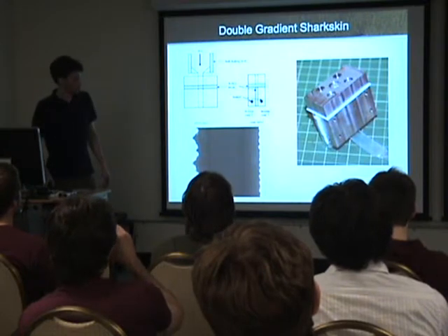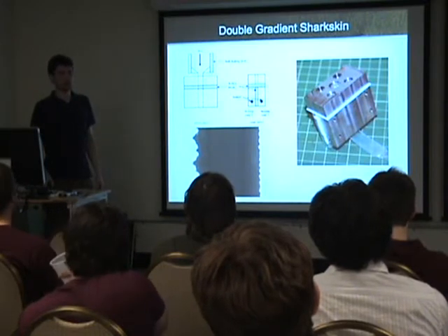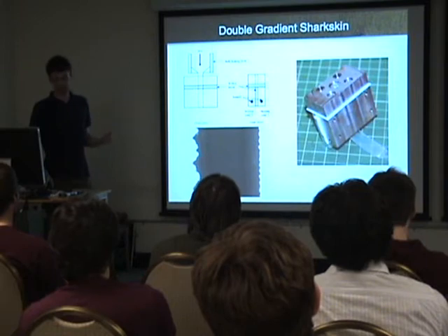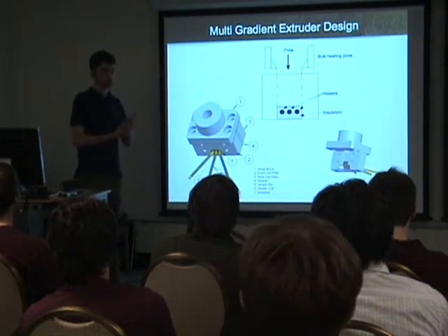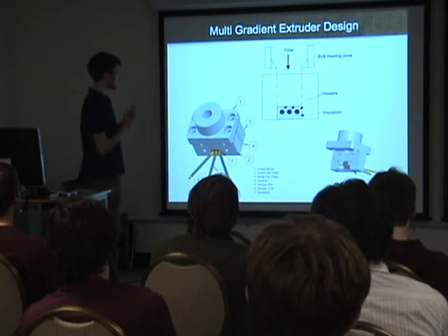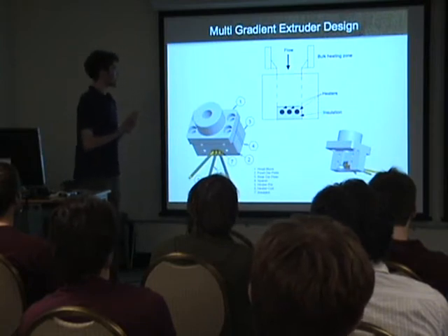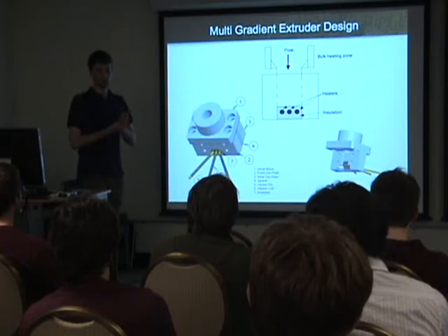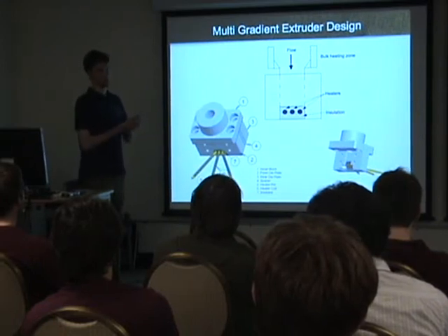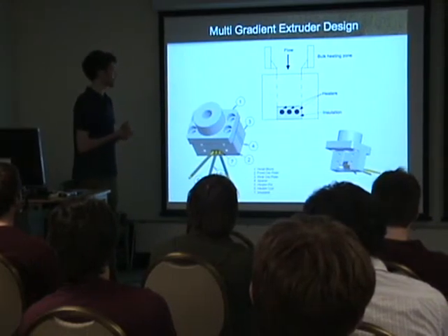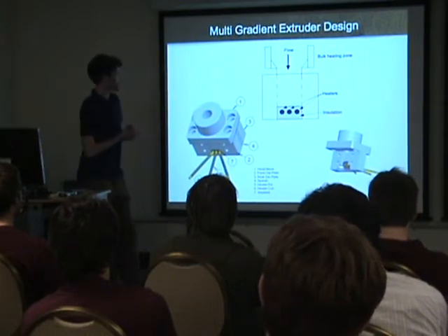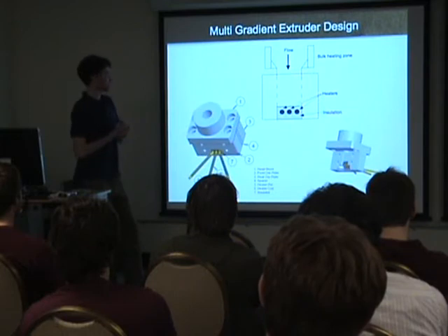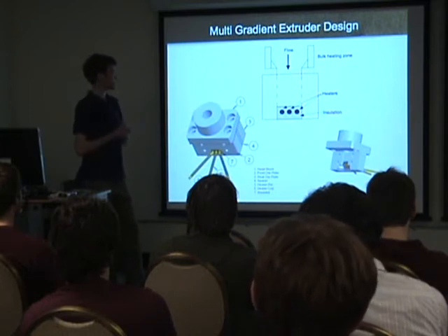So I'm expanding further and asking, how small can we actually get this, and how tightly can we pack these features on a single extrudate plane? We've got some images here of my design. It interfaces with the same extruder barrel as before, so I don't have to deal with that problem. But we're looking at a die with three heater pins, and each heater pin is a temperature-controlled loop. We'll talk more about that later.